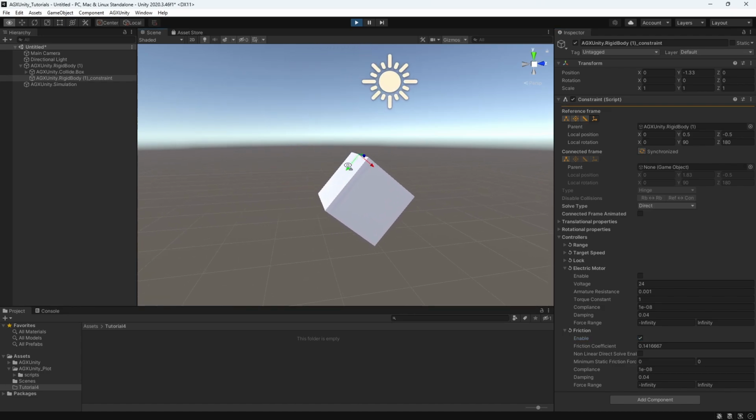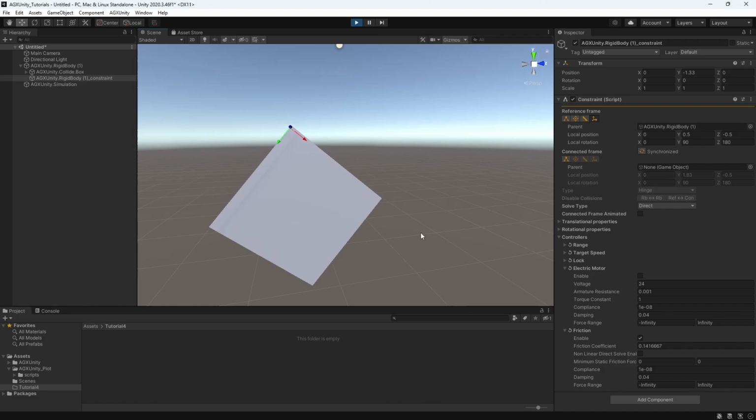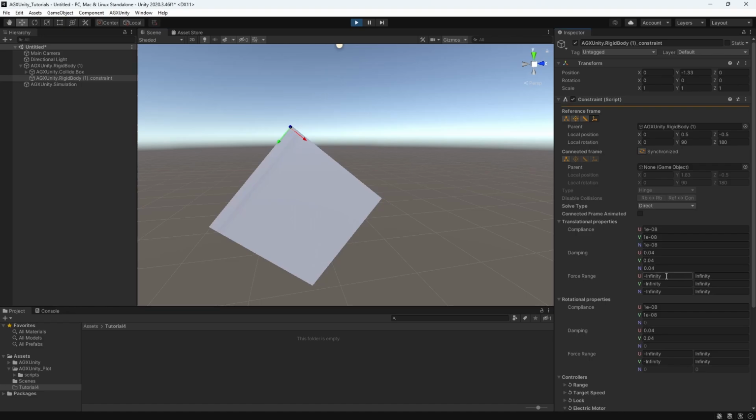One thing that is very important to notice is that when you have a hinge or a rigid body rotating around a hinge at a very high speed, we can see that the constraint becomes violated. And the reason for this is based on the numerical facts of sampling theory and the way that the constraints are being solved. We need to have a much, much higher sampling frequency to resolve a system like this. We usually recommend that you should have a time step that allows for 10 samples in a circle. So if you have an object rotating faster, so that we can't sample it 10 times during one lap, it will not be accurate to use for any sort of engineering measurements. Obviously, you can simulate things rotating faster like that, but you will then see a constraint that is very violated in this axis. Also remember to set the damping according to your time step.